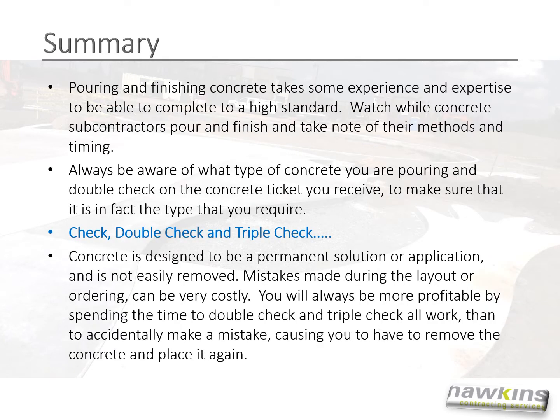In summary, pouring and finishing concrete takes some experience and expertise to be able to complete to a high standard. Watch while concrete subcontractors pour and finish and take note of their methods and timing. Always be aware of what type of concrete you are pouring and double check on the concrete ticket you receive to make sure that it is in fact the type that you require. Check, double check, and triple check.